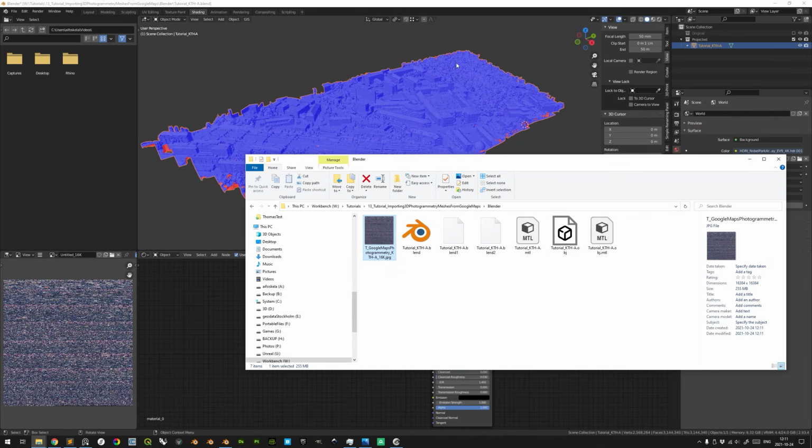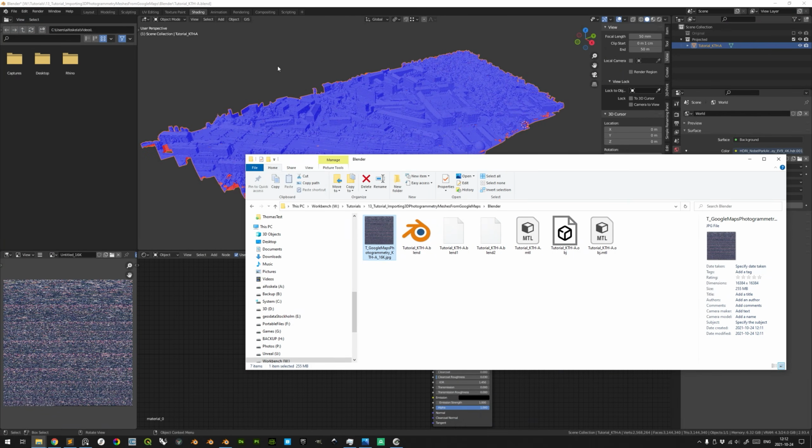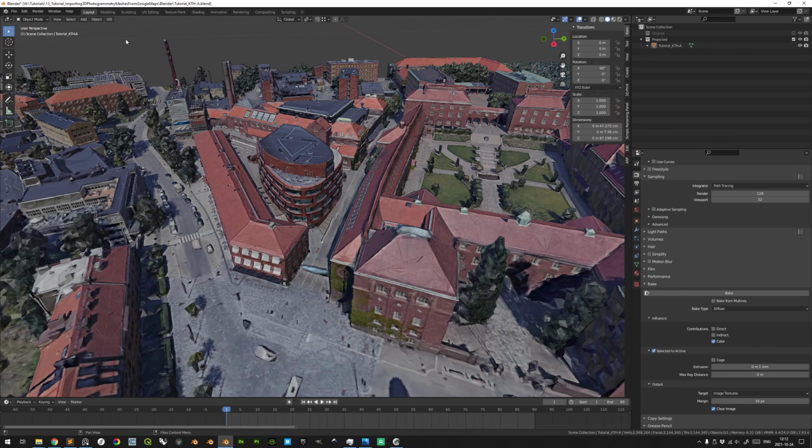Very good. And this texture might look a little confounding, but it is properly mapped to the unwrap that we did in MeshLab. And given that we export the object from Blender with its texture coordinates retained, it can be imported in Rhino or any other program. And as long as you assign this as the diffuse or the base color in that software's material editor, you will get similar results as here in Blender.